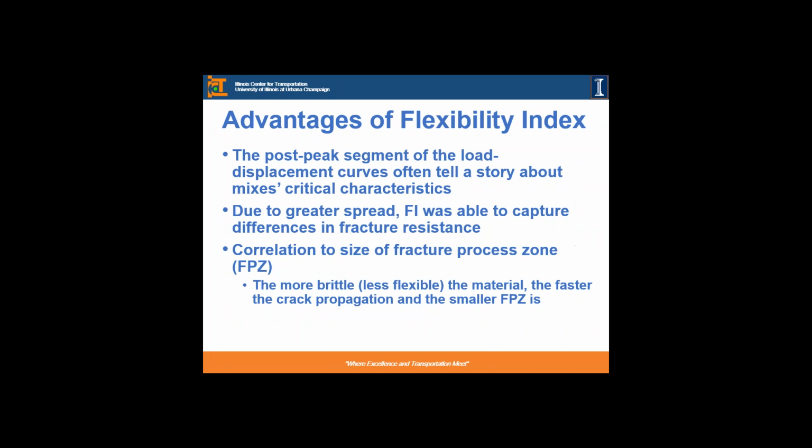Some of the advantages: we really look at the post-peak segment of the load displacement curve. We certainly think that it tells a story about the mixes, about their crack propagation. And you have a greater spread with this flexibility index, and that captures even the small differences between the mixes. Also, it has some correlation to the size of the fracture process zone, which is a fundamental parameter that you can relate this index development to.